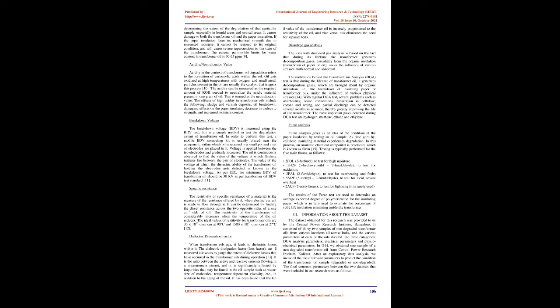Dielectric dissipation factor. When transformer oils age, it leads to dielectric losses within it. The dielectric dissipation factor, loss factor, TAN-D, measured allows us to gauge the extent of dielectric losses that have occurred in the transformer oils during operation. It is the ratio between the active and reactive currents flowing in a measurement circuit, and it is significantly affected by impurities that may be found in the oil sample such as water, size of molecules, temperature-dependent viscosity, etc., in addition to the aging of the oil. It has been found that the TAN-D value of the transformer oil is inversely proportional to the resistivity of the oil, and vice versa. This eliminates the need for separate tests.